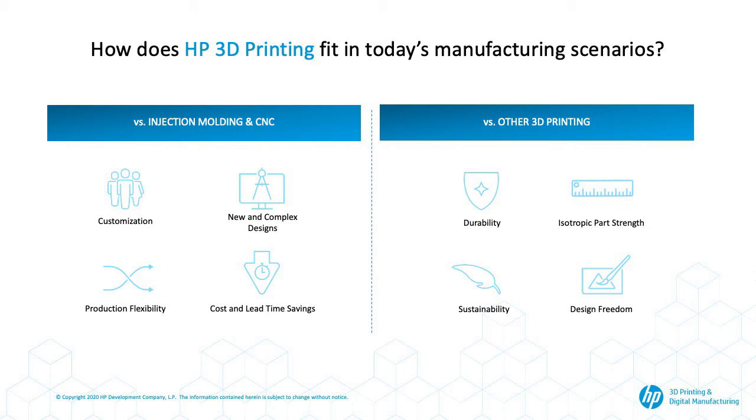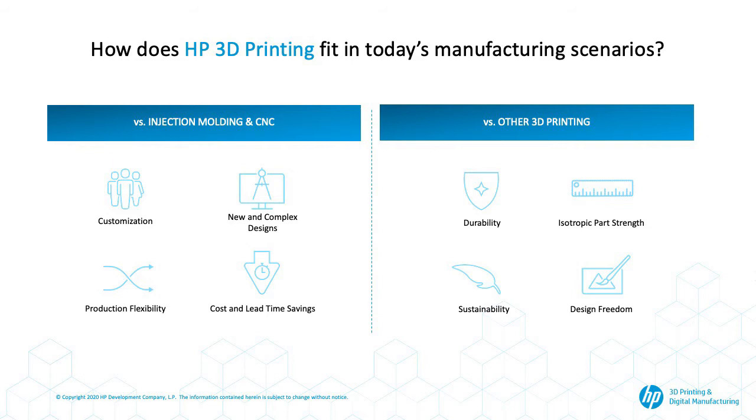You may have experimented with FDM printers, desktop FDM printers that create some of the prototyping parts in general, but what we see with a lot of the layer-by-layer technologies that don't necessarily focus on powder bed is that the strength that you have for the part on the X and Y direction might not essentially be the same on the Z direction. With powder technologies within 3D printing, you essentially are able to keep that same level of strength for X, Y, and Z direction, which increases the durability of the component and enables it to be incorporated into production-ready environments.